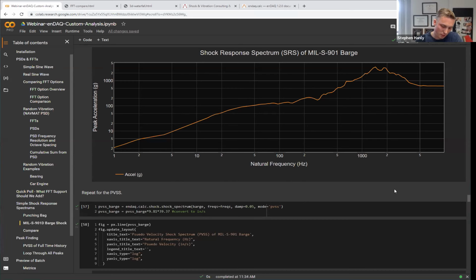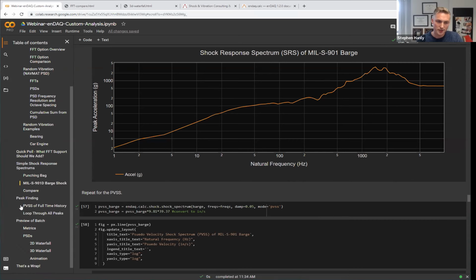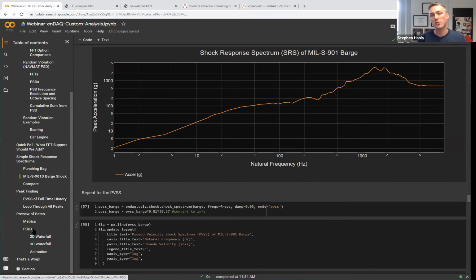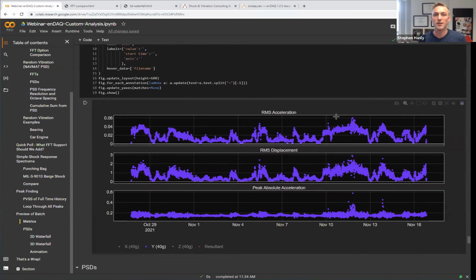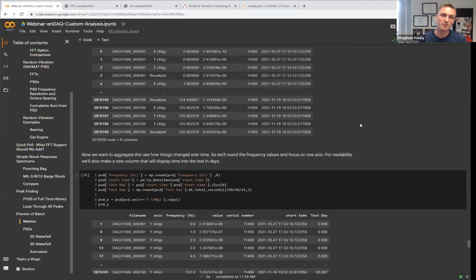that's where I think our batch processing will really come into play and help. If you have a long time history, one thing we do need to add to the batch processing is either doing a bunch of explicit files, or, if you have a big file, separating it into a series of segments. Then you could see an outlier and potentially just remove it when doing the power spectral density. So I think batch processing is going to be how you address that in the future.